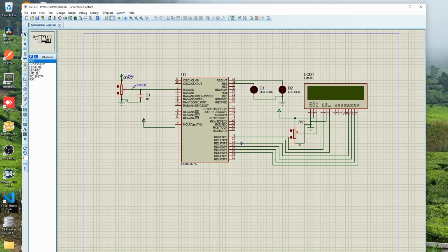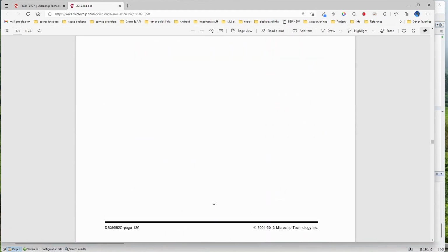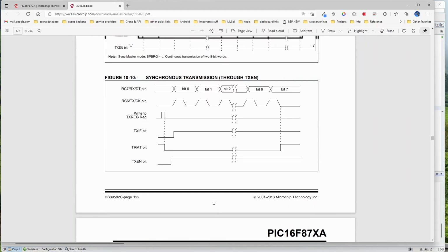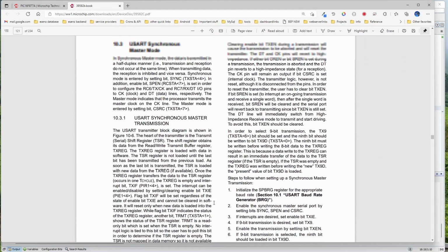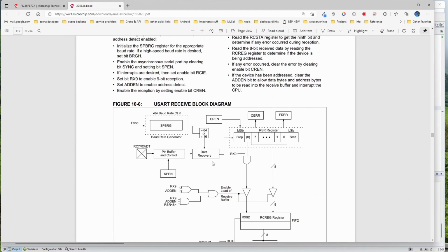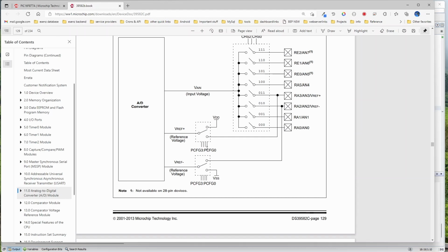Okay, next thing I'll show you is the ADC reference. Till now, we were comparing the analog input to the supply voltage VDD. Sometimes that is not useful. Let's assume that you have a relay in your board, a 5 volt relay. Your supply voltage is correctly 5 volts.